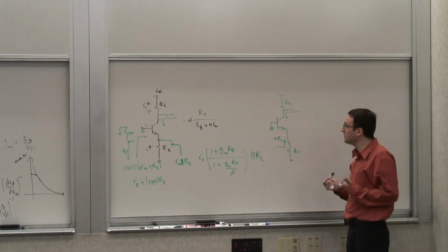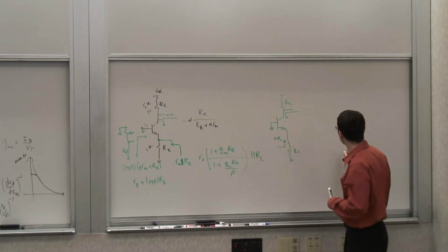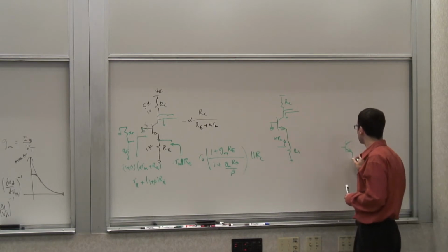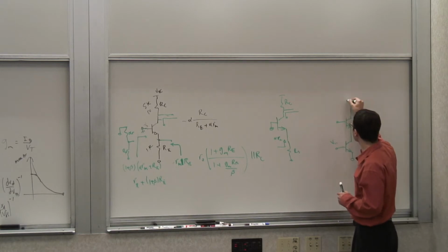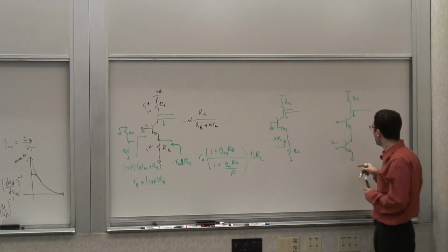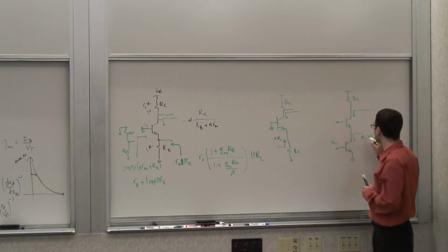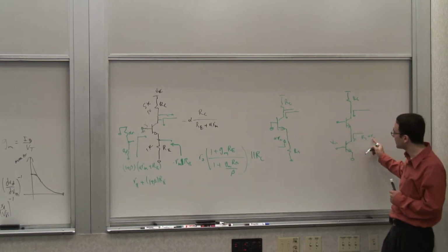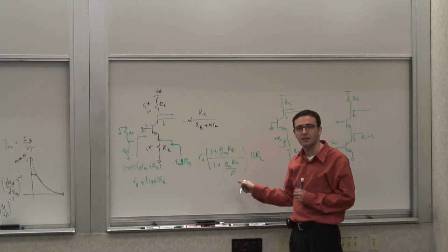So now its output impedance is also similar to that, but now if I drive it with a high impedance source, namely a transistor, a common emitter, I can form the cascode. Now if I look down here, my RE or RS looking down here is simply RO. Therefore, I have to plug RO into this equation, and I get gm RO and gm RO over beta.